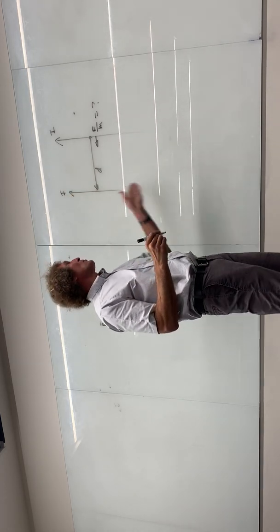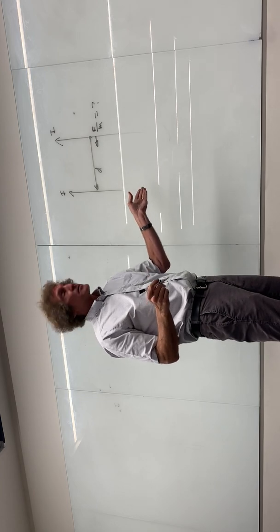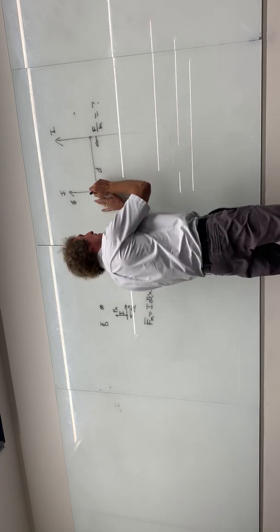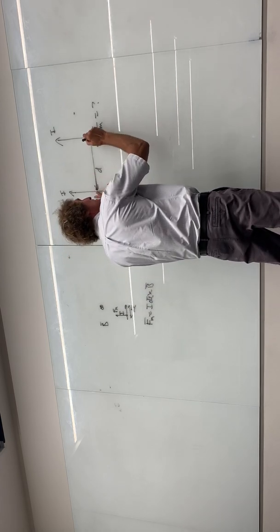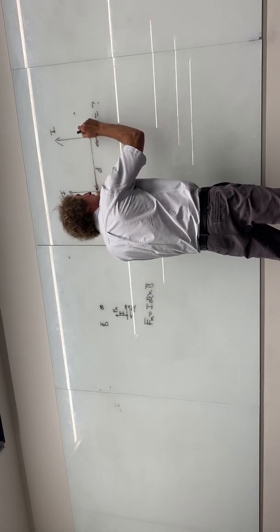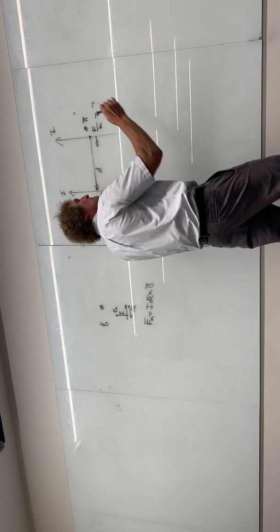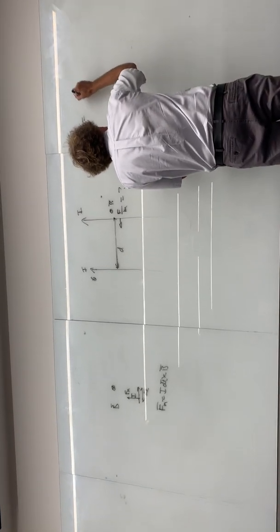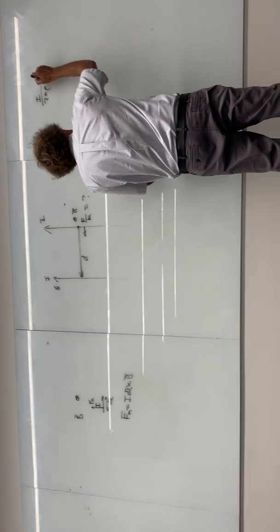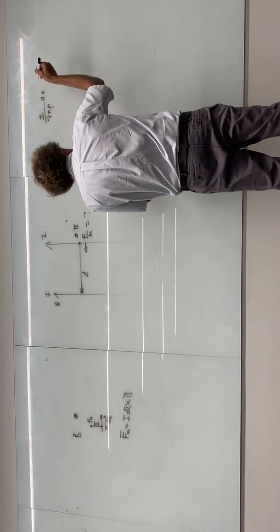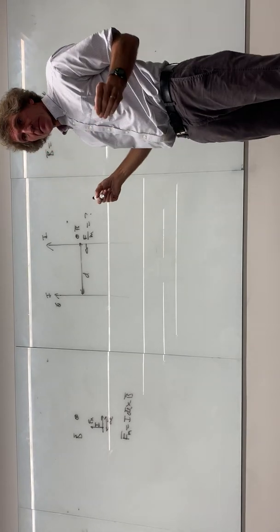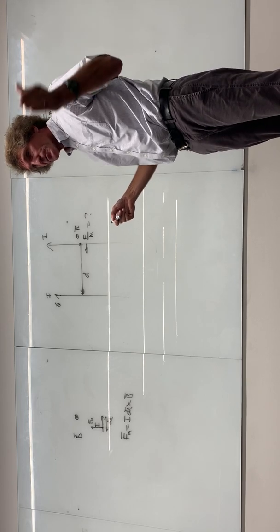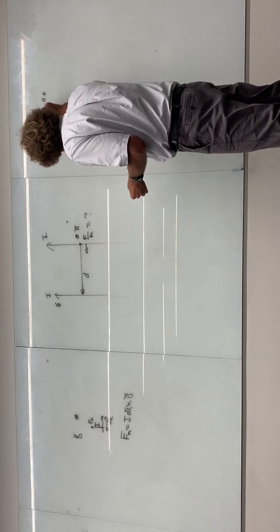Well, you're going to take one wire as the source of the magnetic field. So I'm going to use this as the source of the magnetic field, and I'm going to calculate the magnetic field from this wire at this point. So what I'm going to get is the B field right here. So what would that B field be? Well, we know the H field would be I over 2 pi rho in the A phi direction, or into the board. Do you agree with me? But I wanted the B field. What do I have to do? Multiply it by mu. Actually, mu naught.